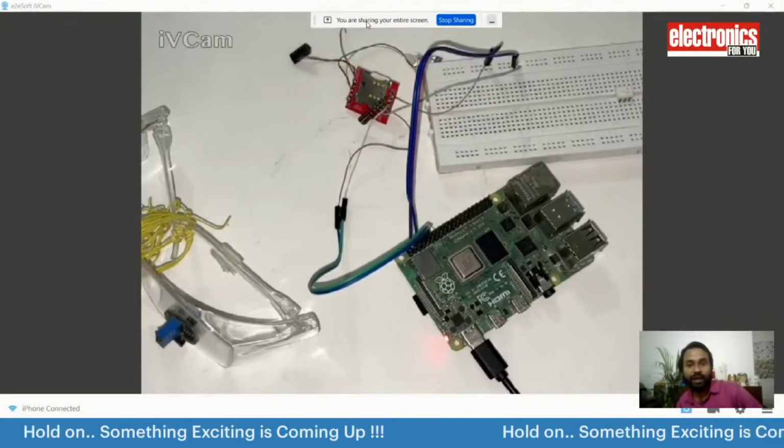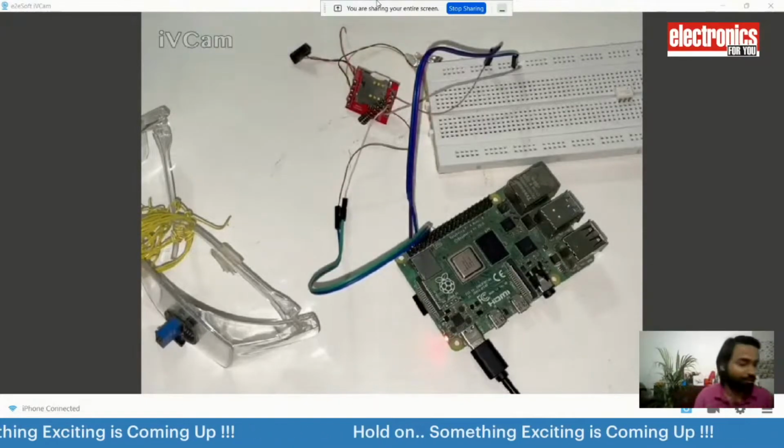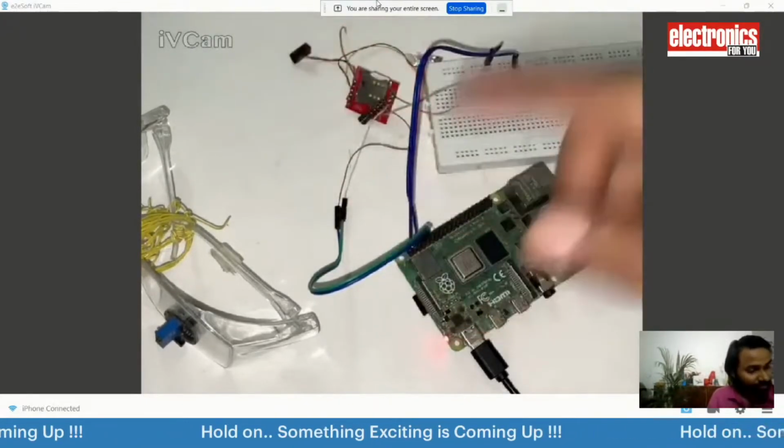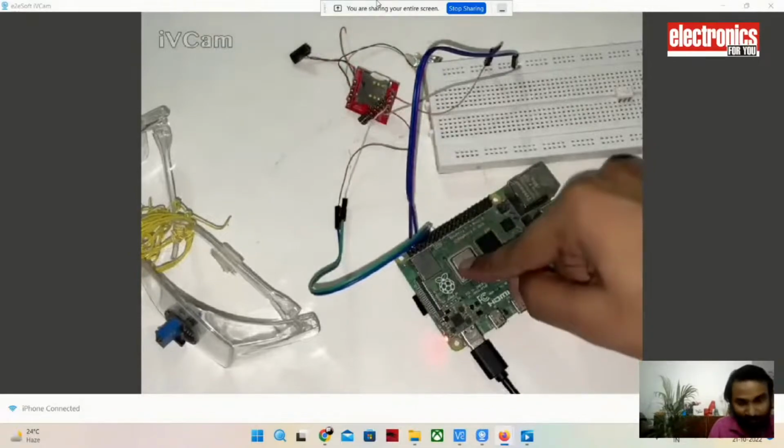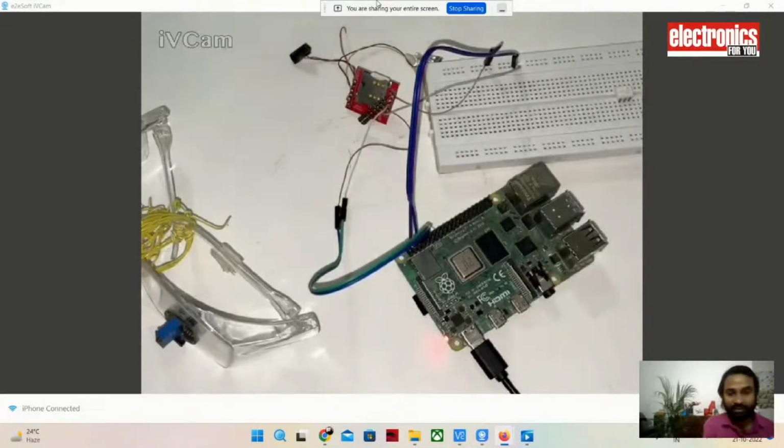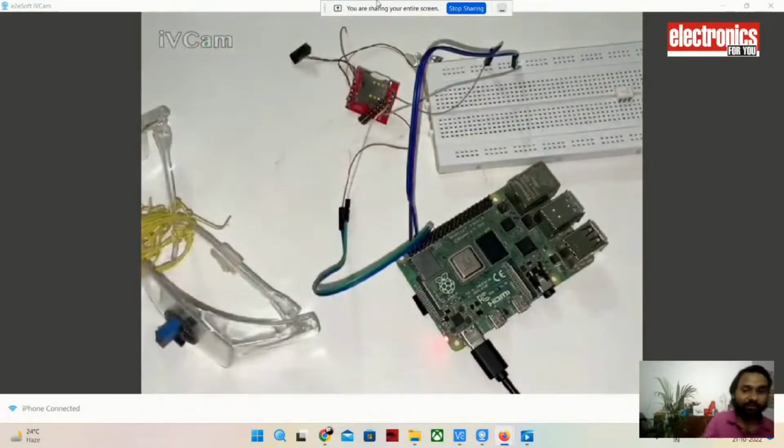It has 2 pins, RX and TX. The RX and TX pins should be connected to the RPi board, and only then will we be able to communicate with it and get messages, calls, or whatever stuff we want to do. We can make code and do those steps on this module. So let's first install the GSM module.